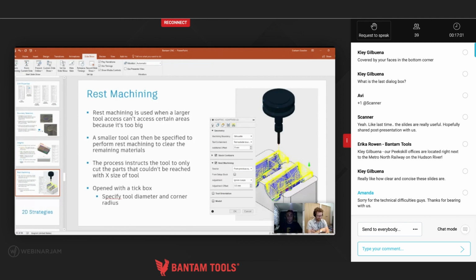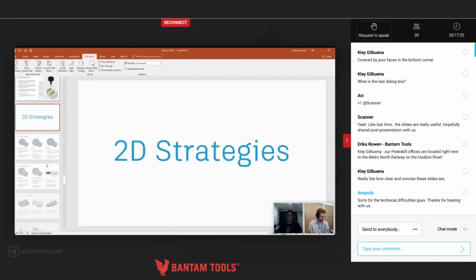By doing that, we won't perform any air machining in the middle here. We'll just focus on the steps that are remaining, cut those out, and do what we call semi-finish. And then from that, we can take a finishing tool and finish the part itself to make sure it's nice and clean and not put loads of stress on the tool. Again, I'll show you more examples of these as we get into the demonstration.